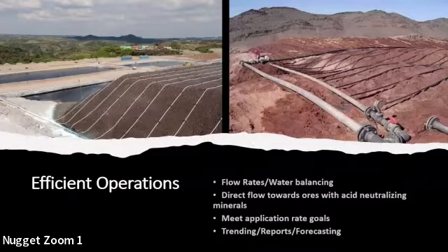In terms of this analysis, we established some criteria to look at in this ore. One is that the saturated hydraulic conductivity is 100 times greater than the forecasted irrigation rate, which is 0.003 GPM per foot squared. The 100x factor is applied to account for variability in the ore material. We have these samples, but they're just grab samples. So accounting for that, accounting for variability in the emitters and irrigation lines, if it's not always perfect across the entire surface of the pad, accounting for precipitation, accounting for uneven surface on the pad. It's really to account for all these unknowns, and so we apply a 100x safety factor here.